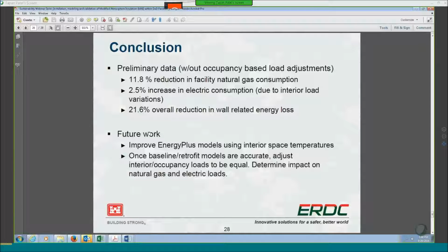We do have some work to do in our EnergyPlus models. As I mentioned, we had some issues with our sensors, and we're working on fixing those. As we learn more from our models, we expect to be able to simplify them. So, for example, if you wanted to use eQuest or something else that wasn't as detailed as EnergyPlus, we expect there are a lot of simplifications you can make to your models to account for much of these variations.